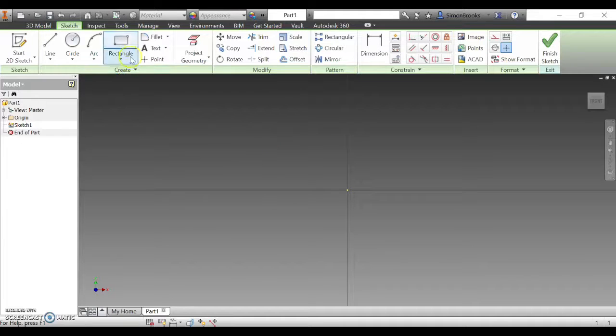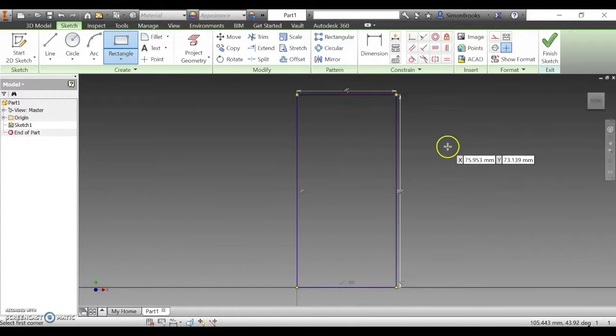So for this, it might be helpful to create a little rectangle first, and we're going to make that 50mm by 100. And we'll center that back up. So that is pretty much our constraint for our pot. You can draw any sort of shape within this little rectangle, and that will be within our constraint.